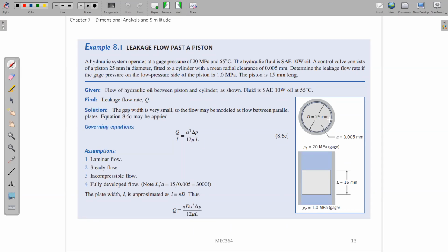So in that case, if you zoom in on a local region of this flow field, it approximately looks like a flow between two straight plates. That's why we can still use our previous solutions for the flow between two stationary, fully developed laminar, infinitely long plates.